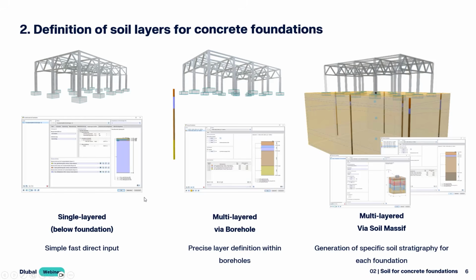This is a fast way of direct input of the soil situation. If you have a layered soil below the foundation and you want to consider and define it, we provide the option to use the borehole dialog. For the add-on concrete foundation, the borehole dialog is provided too, so there's no geotechnical analysis add-on needed for using this solution. There you can go to the borehole as we showed for our advanced half space method, define the soil layers, assign them to the foundations and use it.